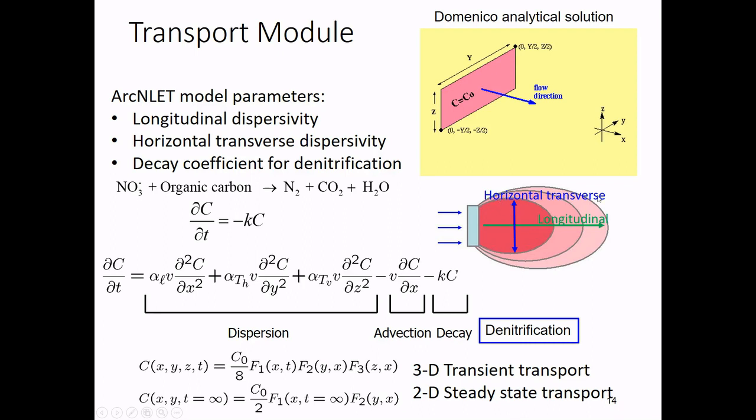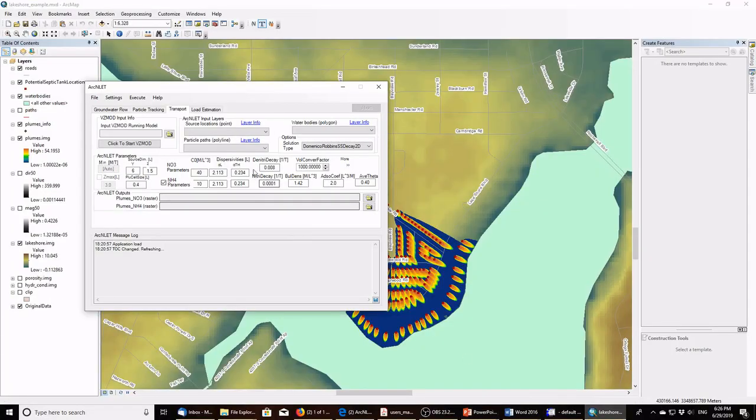So we have a horizontal transverse spread out, and that's alpha_th, where t is transverse and h is horizontal. If it's 3D, we have a vertical transverse, that's alpha_tv. But in our case, we're only simulating 2D flow, and we need a longitudinal dispersivity and a horizontal transverse dispersivity. So that is related to here, dispersivities: alpha_L is longitudinal, alpha_th is the horizontal transverse dispersivity, right here.